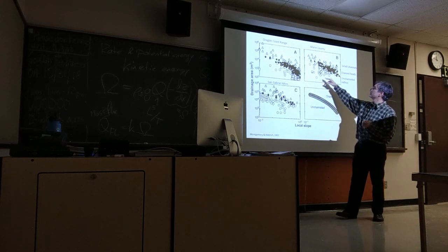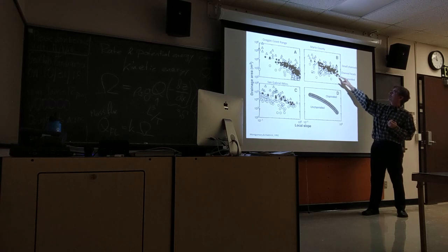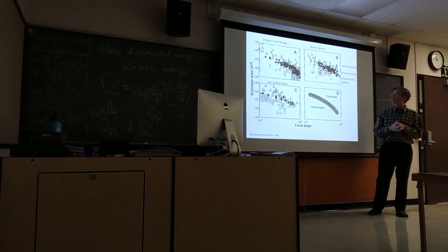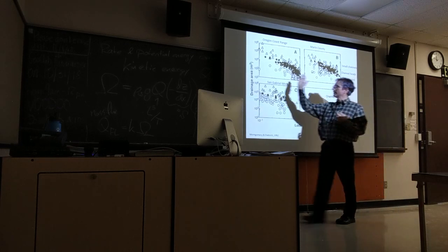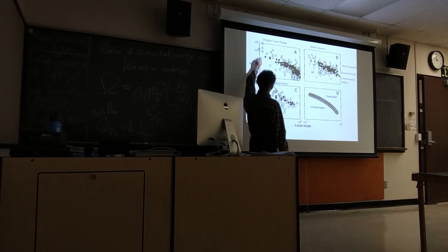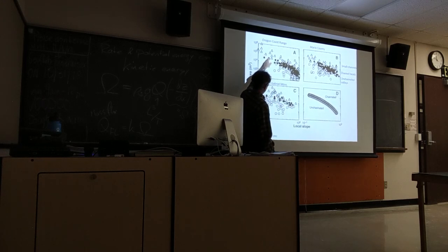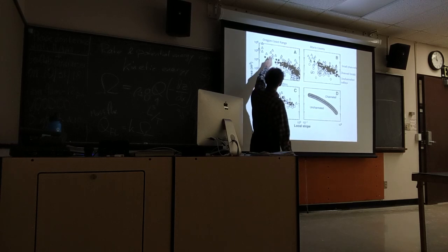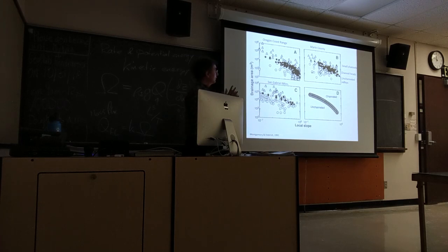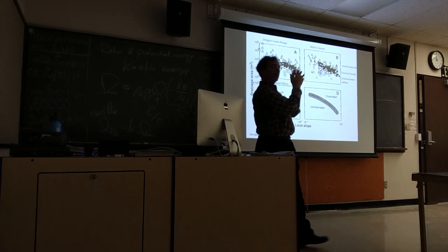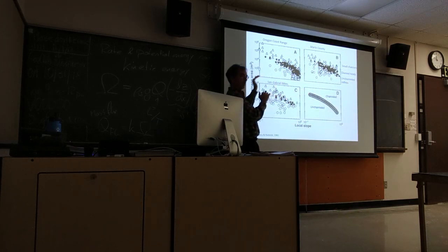These are data from the Oregon Coast Range, the Marin Hills, and the San Gabriel Mountains. The triangles are small channels, the filled circles are channel heads, the open circles are unchanneled valleys. And we've got slope on this axis, drainage area on this axis. And what we see is that for all these different channel heads, if I've got a smaller slope, then I need a bigger area. If I've got a bigger slope, then I need a smaller contributing area for a channel head. So it would appear then that there is some relationship in terms of where the channel head is located, maybe even where channels are in general in this sort of space.